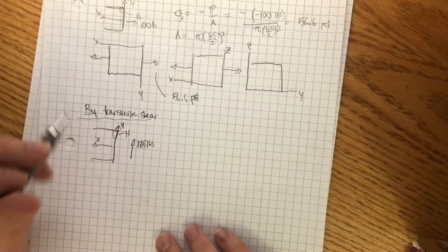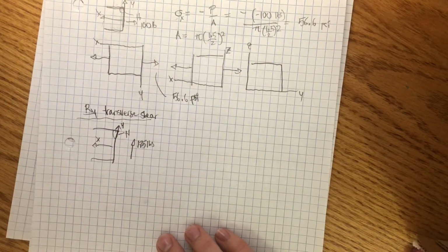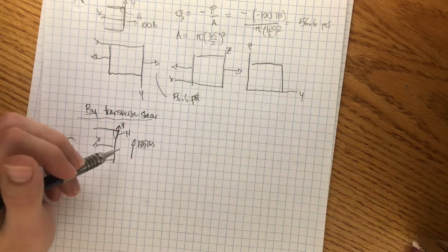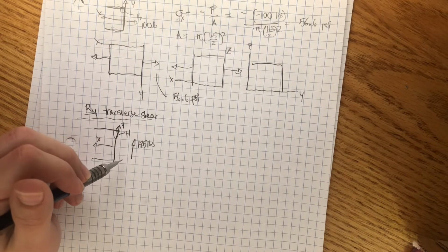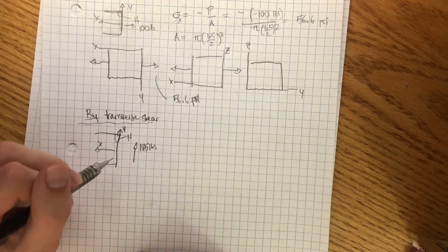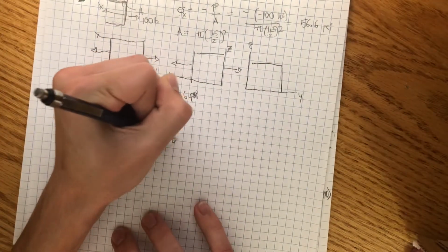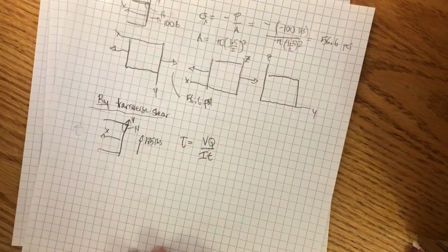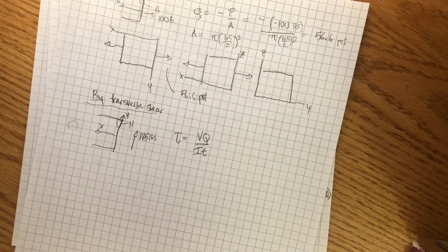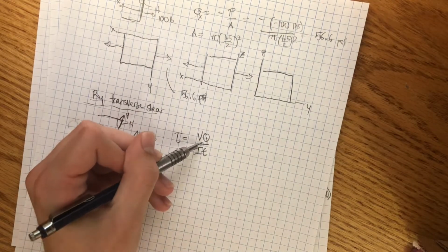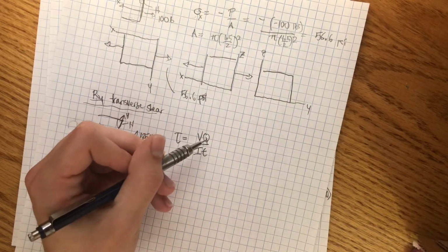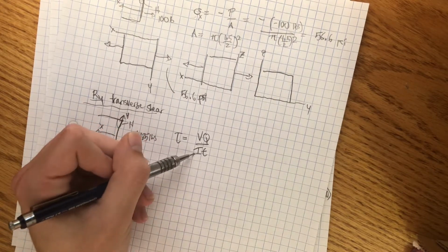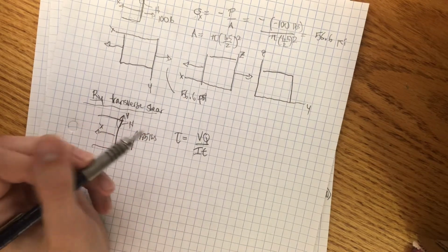And the thing is with these shear forces, specifically these transverse shear forces right here that come from lateral forces specifically, you want to use the formula tau equals VQ over IT. And that is the shear force, right, times the first moment of area over the area moment of inertia times the thickness of the object.